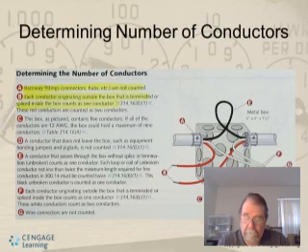If all of the conductors are 12 gauge, the box could hold a maximum of 9 conductors. It's a 21 cubic inch box, because we already know that, we figured it out. It's a 4 by 4 by 1.5. The chart shows what's 21 cubic inch. So with 12 gauge conductors, you can have 9 conductors in that box, I think.